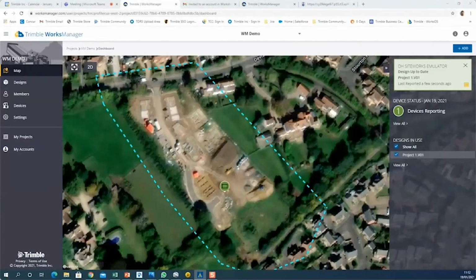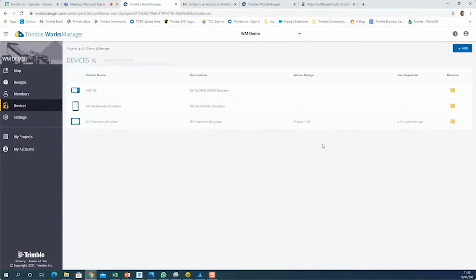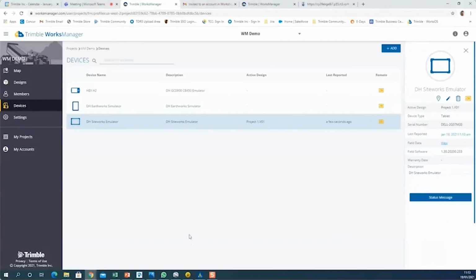Yeah. So the way Trimble operate, we work on work orders, which are daily duties. So you can create these and send those out to the engineer. So today your job is to do an OGL survey, and you give him instructions what to do, and those will come down to the logger as well, and then the data will come back at the end of the day to create a surface from the information he's recorded. Equally, the machine has that option as well. The machine can record, can be given work orders and receive work order information back. Yeah, exactly. Which is useful.